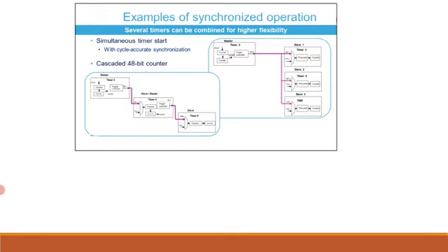The second example shows how to create a 48-bit timer by cascading 3 timers. Here the update event generated on counter rollover is used as the input clock for the following slave timer, so that timer 3's counter holds the least significant 16 bits. Timer 2's counter holds the medium bits, that is bits 16 to 31, and timer 9's counter holds the upper bits from bit 32 to bit 47.